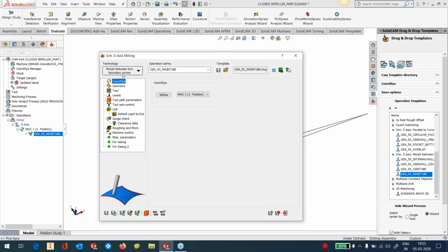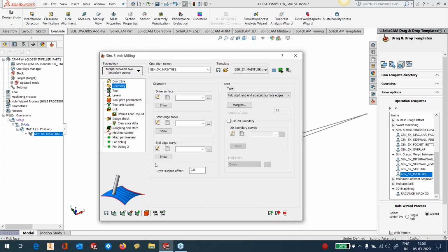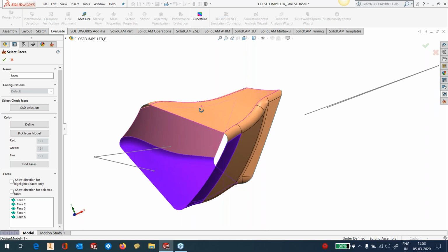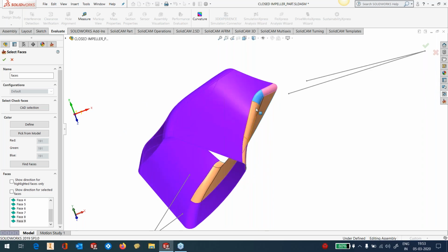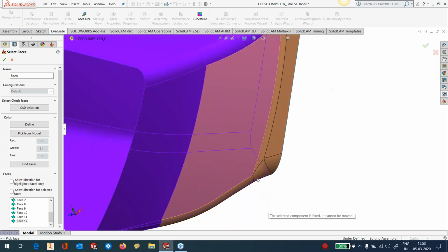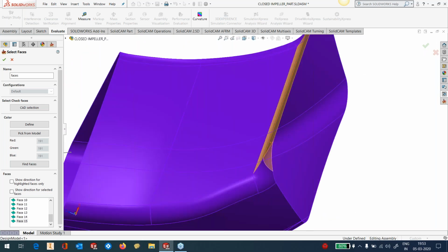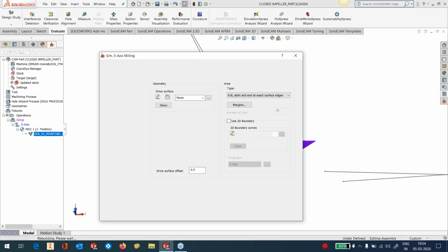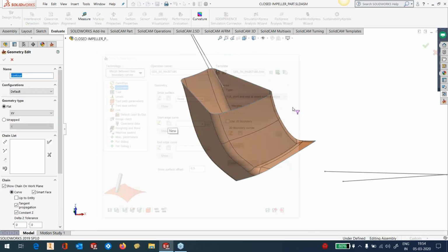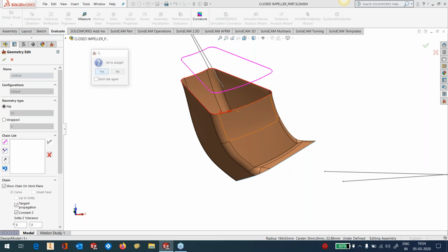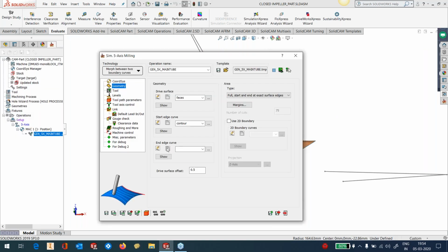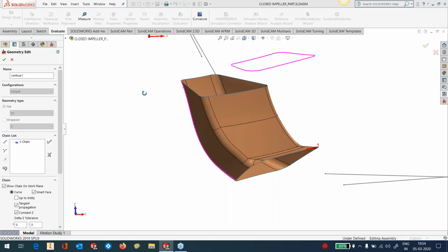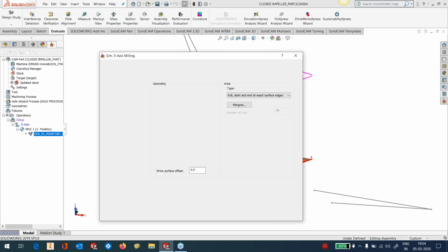So what do I have here? It's morphed between two curves. So I'll pick my drive surfaces, which are these. You can give a color and make this picking very easy. Since I have got two bodies of the same color, I would rather pick them manually. Okay, so 17 faces are picked on one side. Start curve, the upper curve, this can be quick because it's a plane. It was cut with a plane rather. Okay, that's also done because that also was trimmed with a plane, so you can get it very easily.